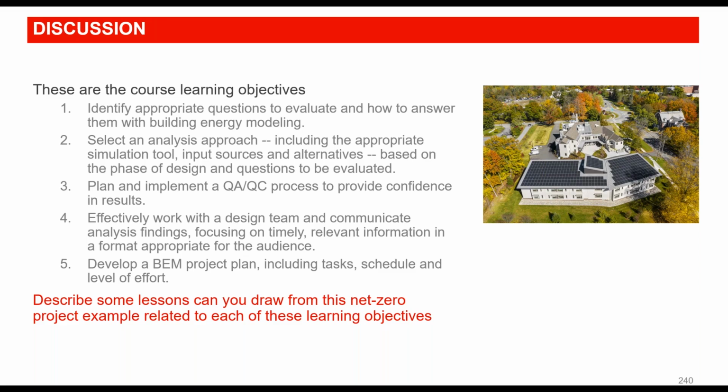But for existing buildings, there's always going to be a degradation factor applied to the effectiveness or efficiency of a compressor or something like that. Depending on the type of equipment, it might be a few percent a year over the course of a lifetime.